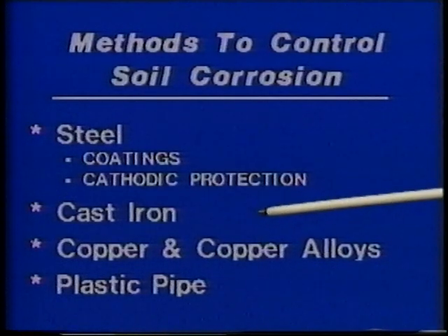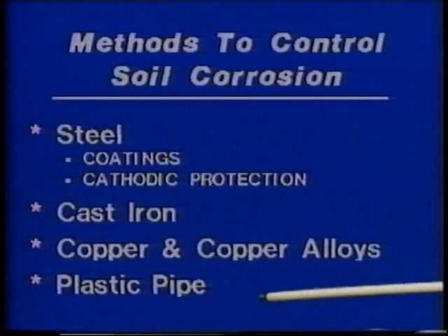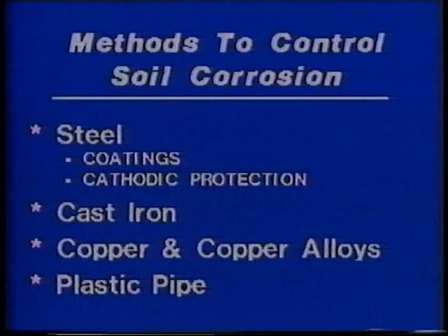We can go to cast iron. We can go to more corrosion-resistant alloys, copper alloys, much more corrosion-resistant in soils, or we can go to non-metallics. There is a much greater increase in the use of PVC pipe and other plastic pipe for applications of materials in buried structures.